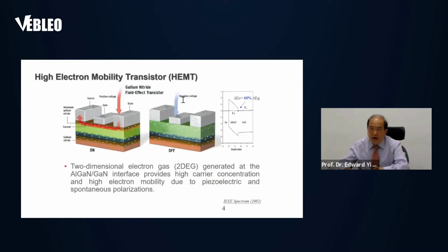Okay, the high electron mobility transistors, which I can give a little introduction. The material is usually formed by AlGaN and GaN, and due to the band discontinuity at the interface, a 2DEG is formed. That allows electrons to be driven to the interface, and the interface forms a quantum well, and these electrons can move in the quantum well without scattering and give a very high mobility.